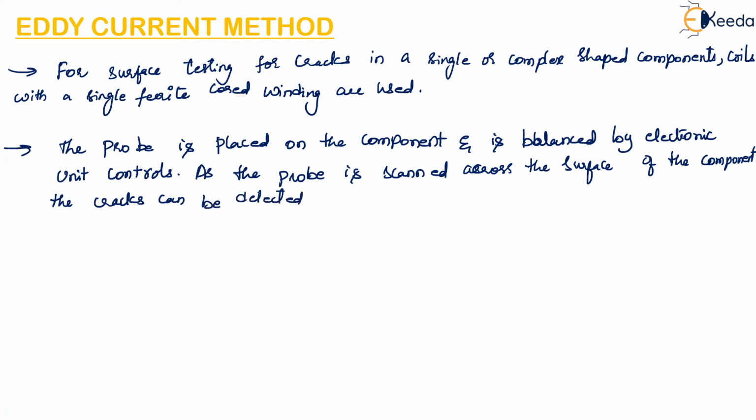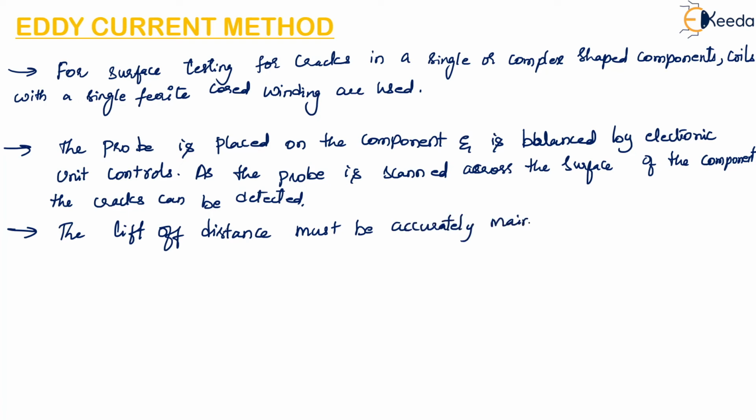So here in the first figure, we have to maintain the lift-off distance accurately. The lift-off distance, that is nothing but the distance between the probe and the surface of the component which we are testing, must be accurately maintained for accurate results.